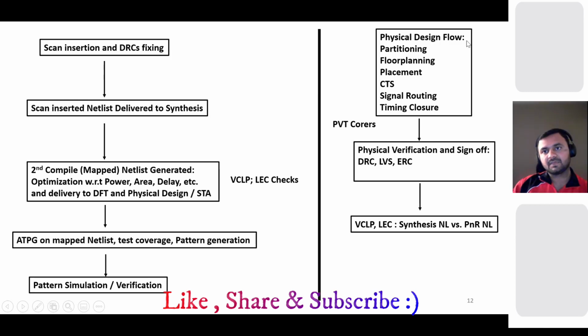And in parallel, since they have delivered to the physical design team for their flow, they will also start with the partitioning. They will partition your chip. They will do the floor planning, placement, clock tree synthesis, signal routing, and timing closure. So many things they will also do on the same mapped netlist. So the things happen in parallel.